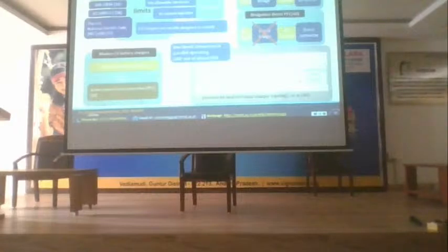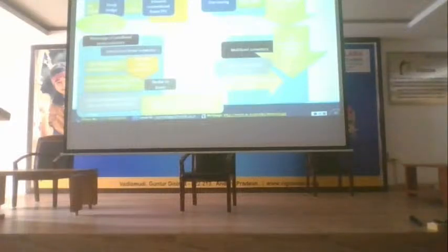because with interleaving we can increase the power handling capability, and also there is current sharing, and second thing the ripple component will be low when we are interleaving. Right, but in the next slide we'll see that there is some advanced topology. This is the basic one which we have discussed, like one is an HDC average output that will be given to the conventional boost.